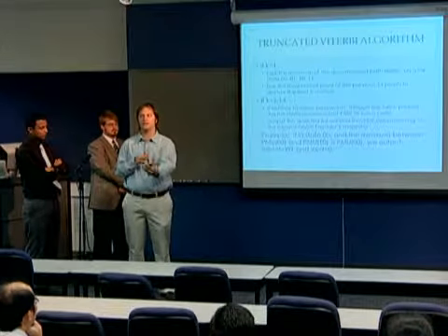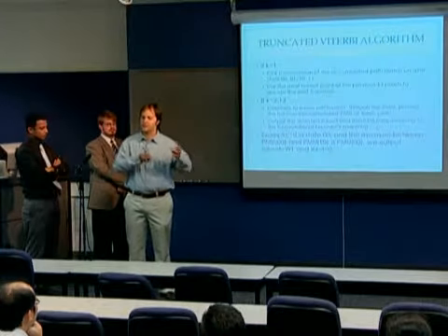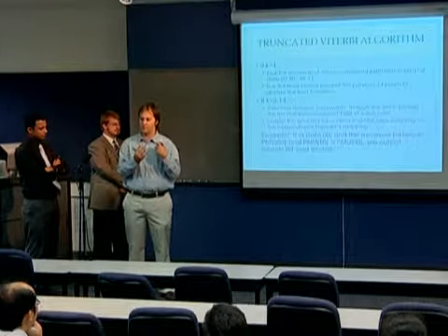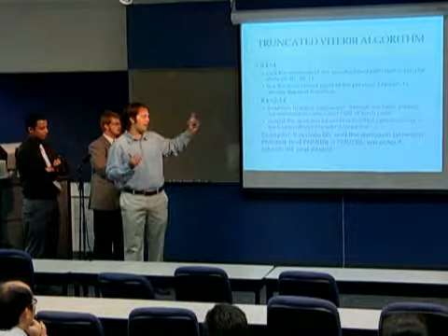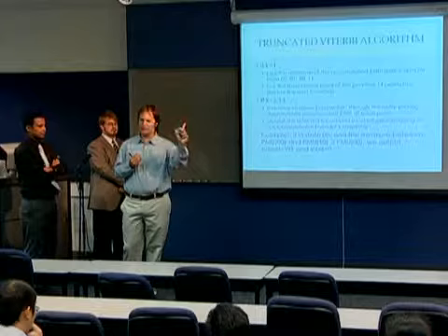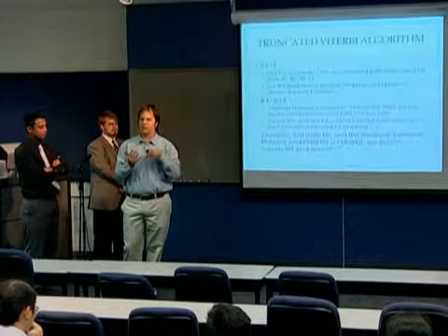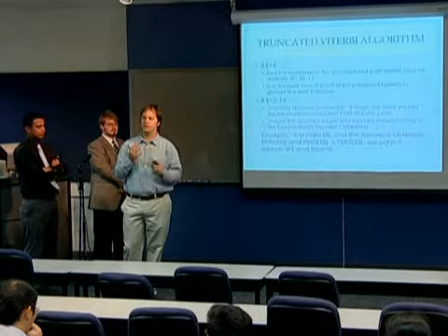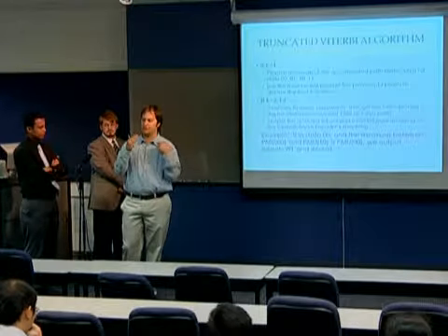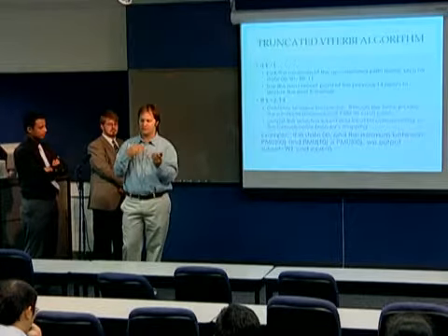Basically, within each subset we have 4 minimum distances. Those 4 minimum distances each correspond to a point. We take those 4 points and we remember them for now, because now we know which subset it was. So, okay, we now know it was from the W subset. So we pick the index corresponding to the point that had the minimum within the W subset, the difference between the W subset and the received signal, Euclidean distance wise.